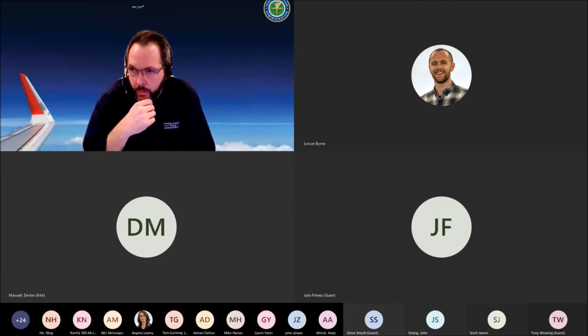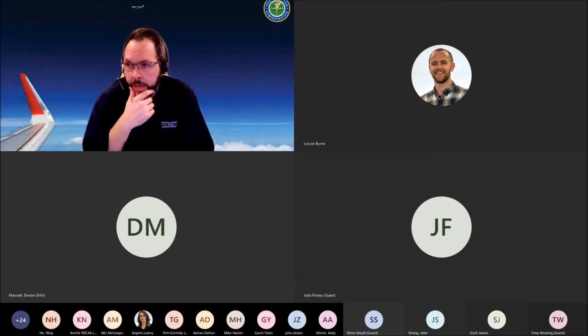Now, your question is really about whether we would mandate both top and bottom mount, and it is something that Canada is looking at. I do believe they are looking at mandating top mounted antennas because they're really using space-based ADS-B today operationally over the North Atlantic, and they're looking at it for other applications as well. I do think they're looking at a mandate. I don't think the US will.